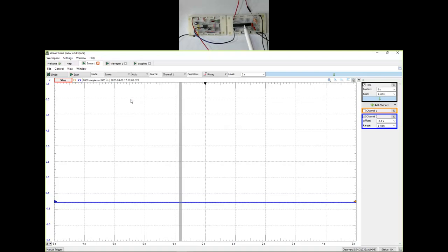It gets flipped, and operates this negative edge triggered flip-flop counter to make this into a positive edge triggered counter based off of the switch. So a few connections to make. I need the power and ground for the counter as well, the board itself. So I'm going to connect the red wire to this supply there, and I'm going to connect the ground to ground here.